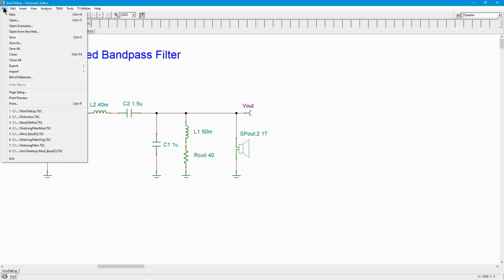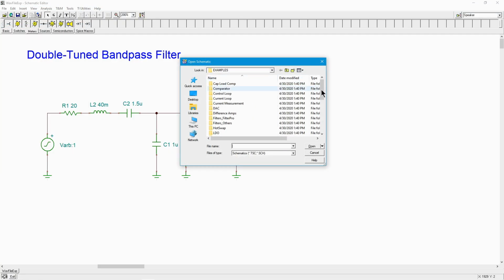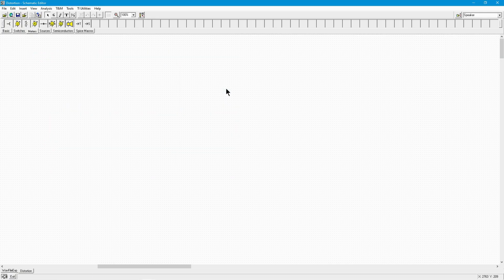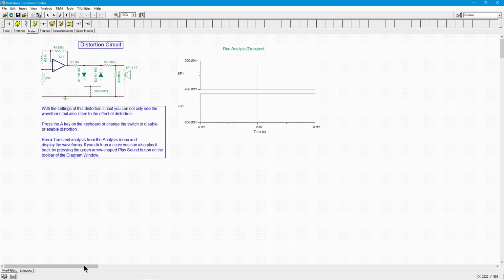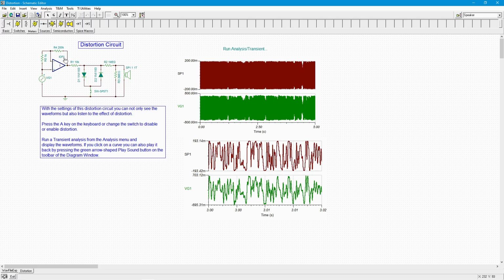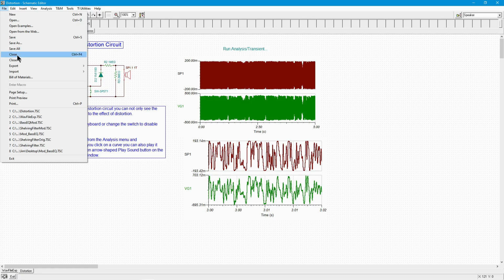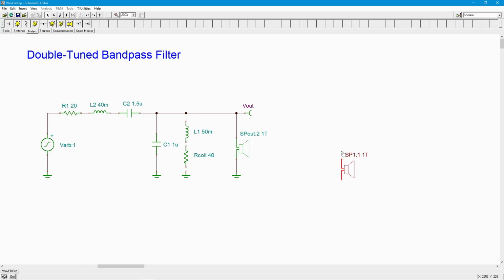What you do is, the proper version of this does exist in the examples directory. So you open up examples, go to the bottom, and you'll see something called wave file examples. Click on this, and there's a bunch of these things. So for example, you can grab distortion, and this is going to open up, there it is, a little distortion circuit, pretty simple circuit, and here's the thing you want. So you just grab this, copy it. Okay, I'm going to close this because I don't need it anymore. And then you can paste it in. Right, Control V, bonk. All right. So this is the device that you would place in here. That's how I got this.